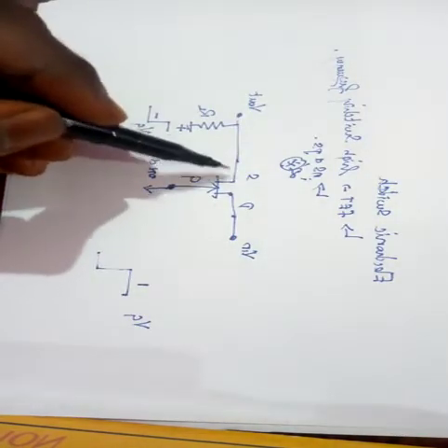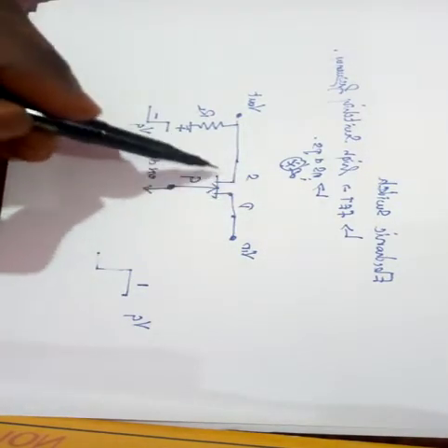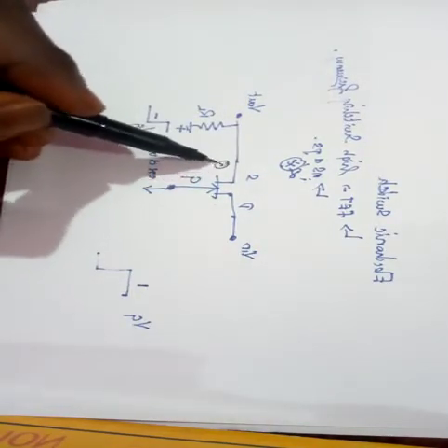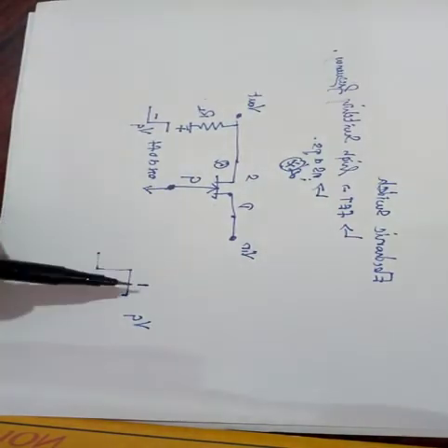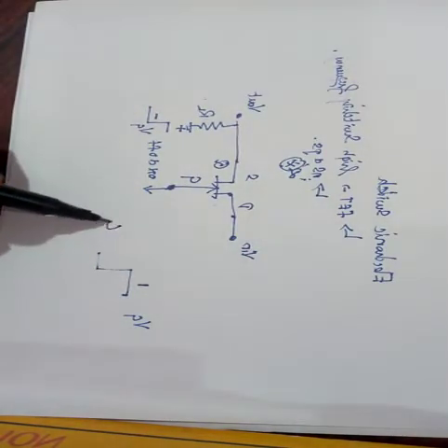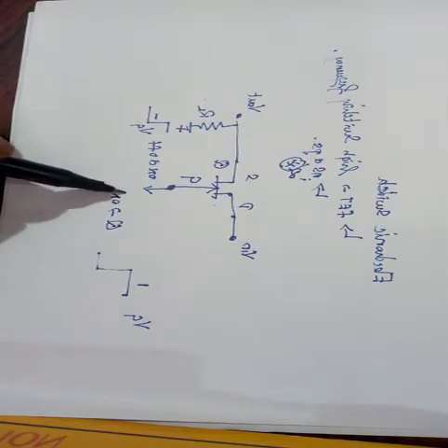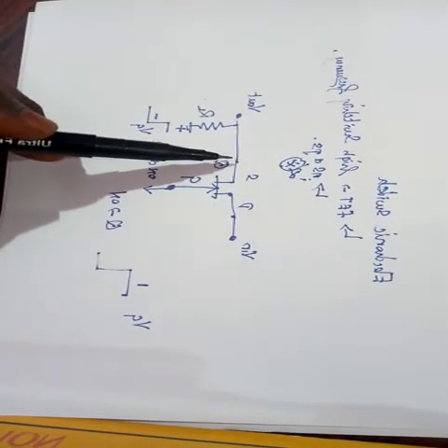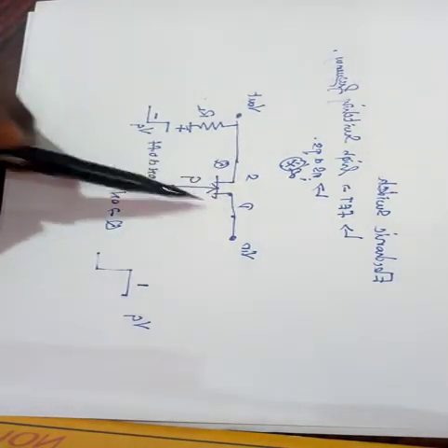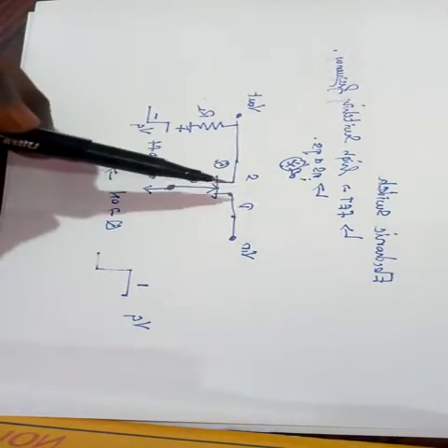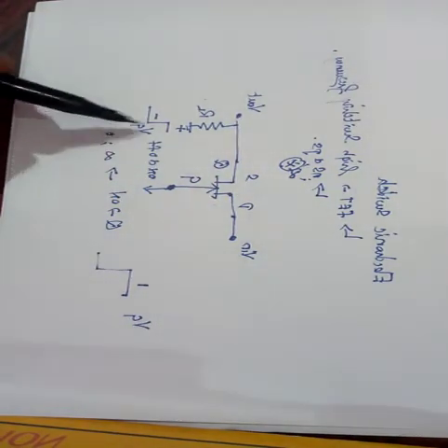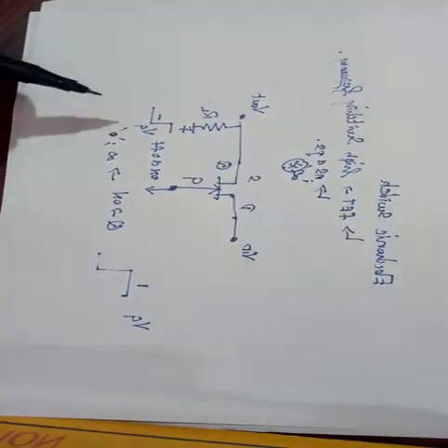Let me say the FET is considered as Q. When Vg goes to 1, the square pulse is high, then the transistor Q is in the on state. As I said, during the off state of the FET, it offers infinite resistance, and during the on state it is a short circuit, so it offers zero resistance.